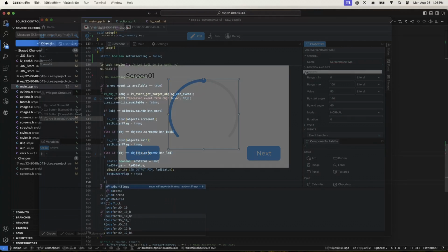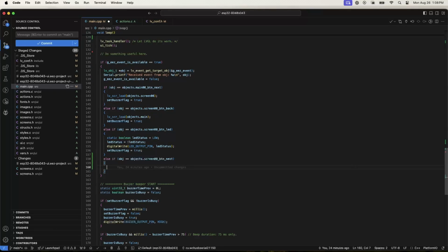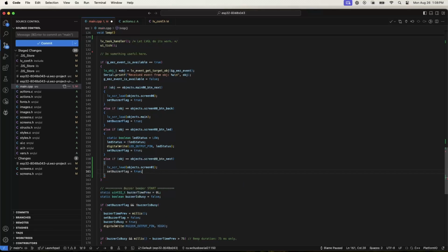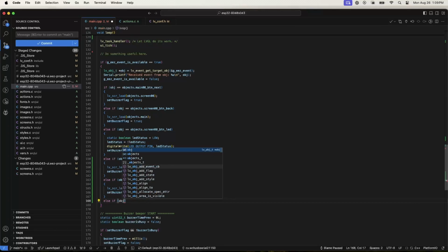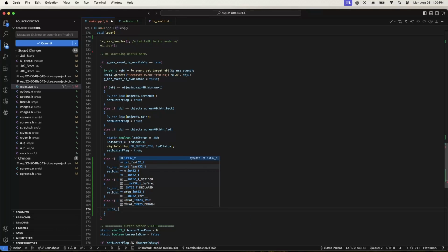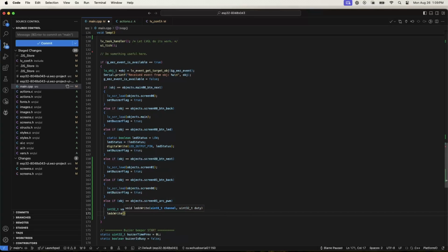We avoid manually modifying the LVGL code generated by EEZ Studio, as these changes would be overwritten with each update to the design. Additionally, the process is simplified by eliminating the need for tedious and error-prone manual copying and pasting of multiple files during UI development. Visual Studio Code's autocomplete feature further enhances efficiency by automatically detecting and listing widget names from the generated UI. This method enables us to efficiently develop, test, maintain, and scale GUI applications, making the process of creating a polished, interactive display both manageable and effective.